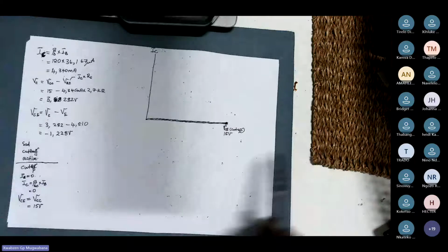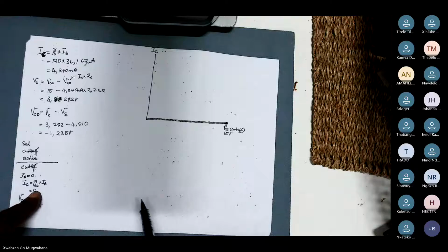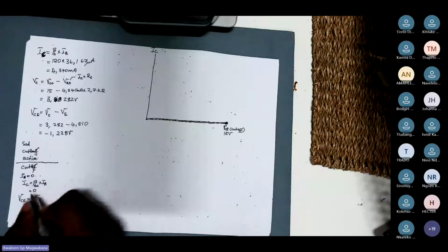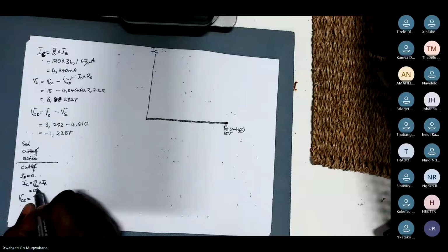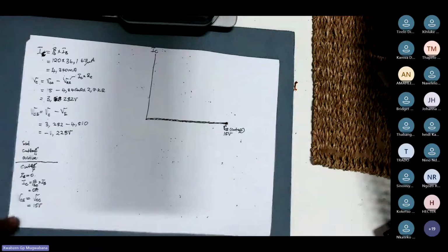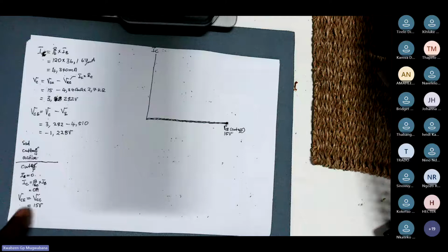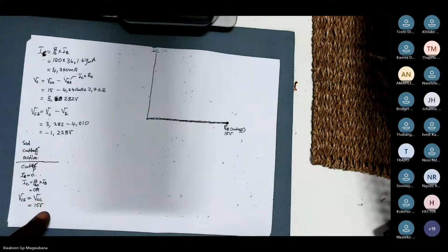Which means we are here. Because IB is 0, and 0 multiplied by anything is 0, here you have got 0 amps. Once IC is 0, your VCE will be given by your VCC. Do we understand each other?